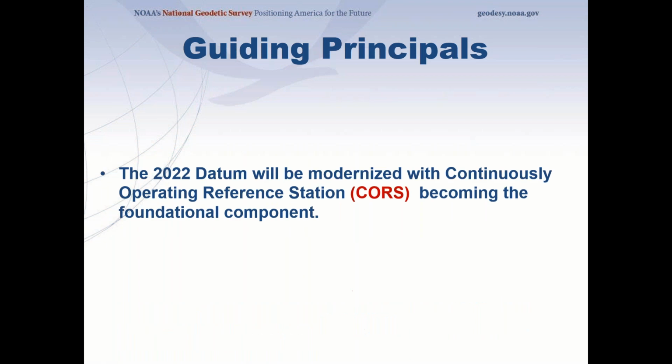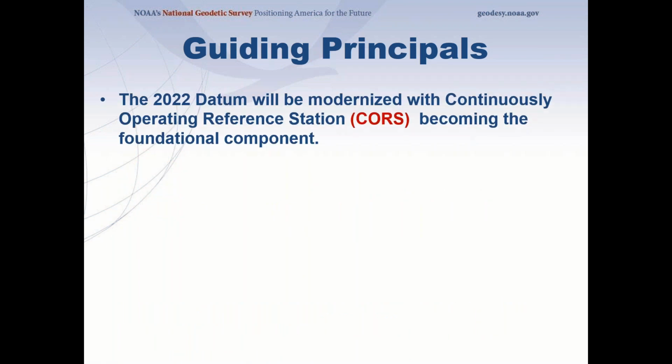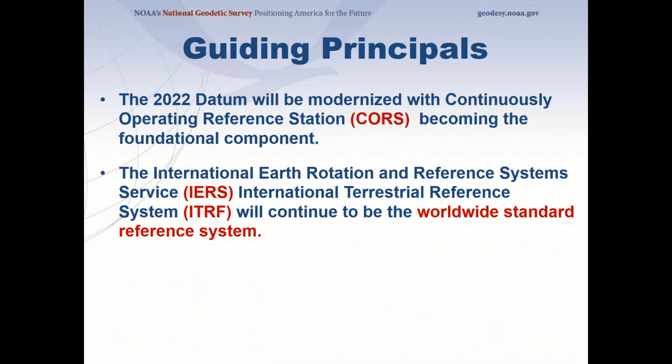So the guiding principles for this whole new surveying system we're going to come up with in the 2022 datum is that we're going to use Continuously Operating Reference Stations as the foundational component of the datum. We're going to align everything to the International Terrestrial Reference Frame, or ITRF, which is a worldwide standard that's used by all the countries.